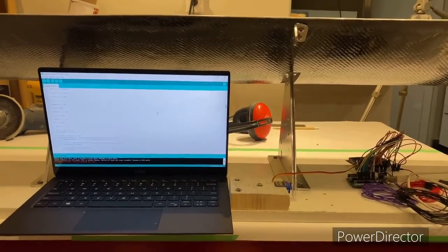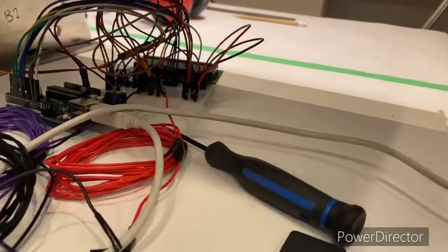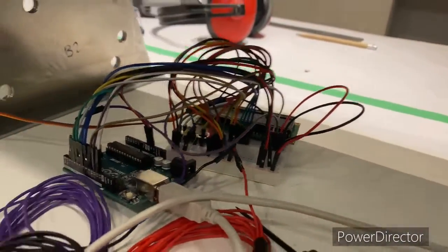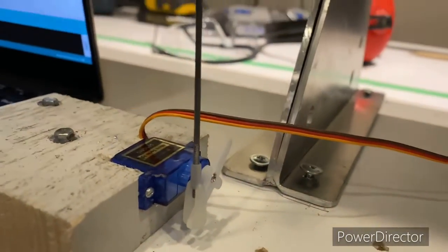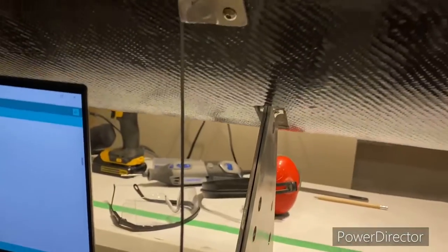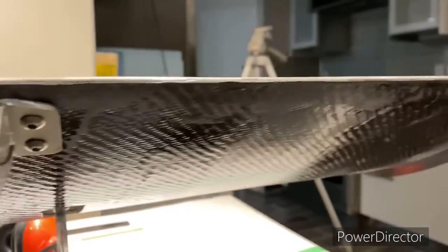The project was a success and functions, although only at speeds below 99 km per hour. Due to hardware limitations, it's impossible to rotate the wing beyond this speed. Although it works as a wing and a difference can be felt while driving, there is missed potential regarding efficiency, as the wing cannot be rotated to a low drag position when it's needed most.